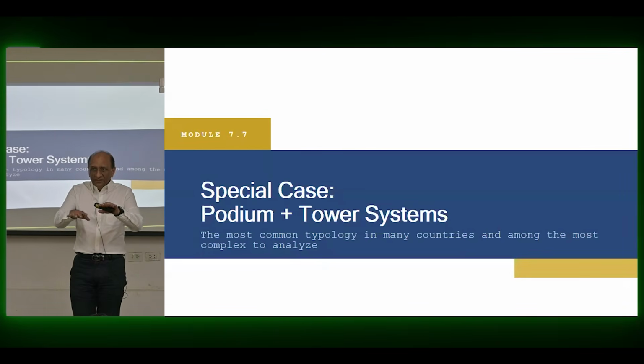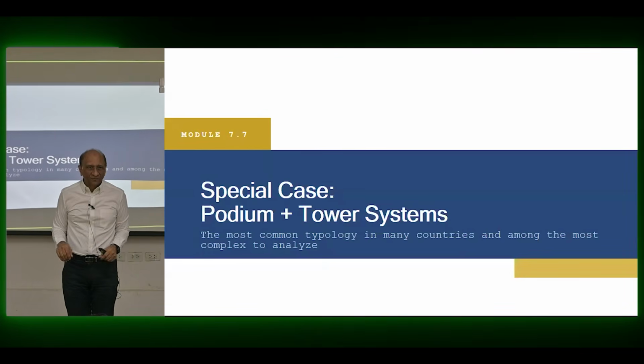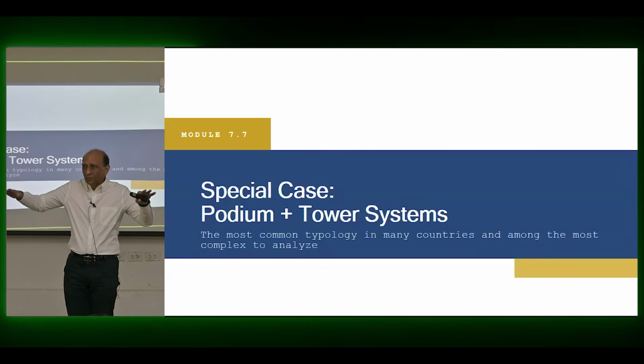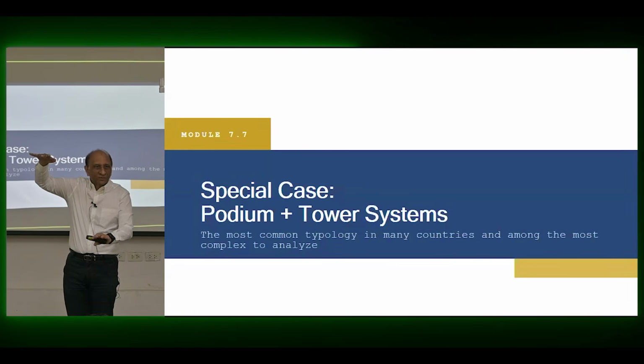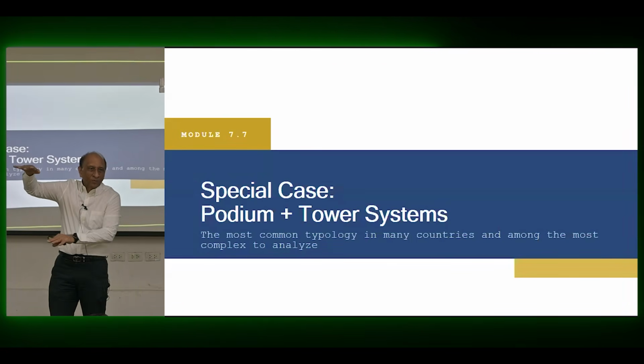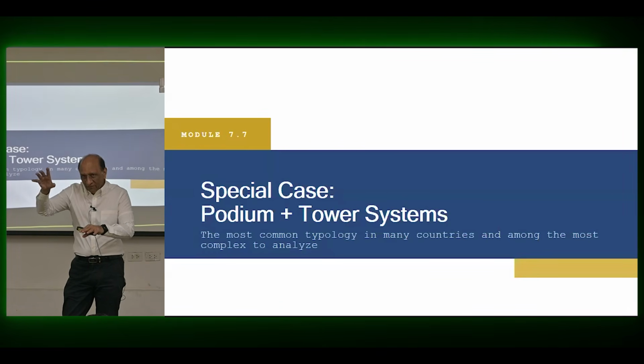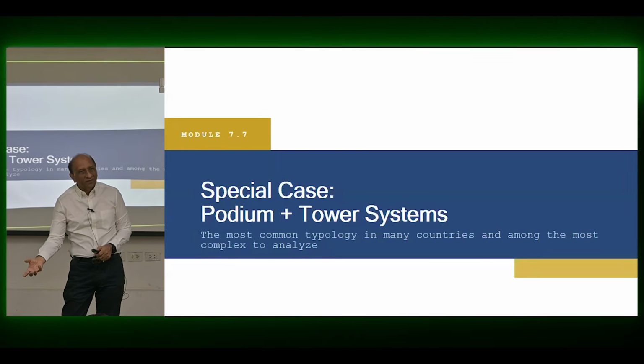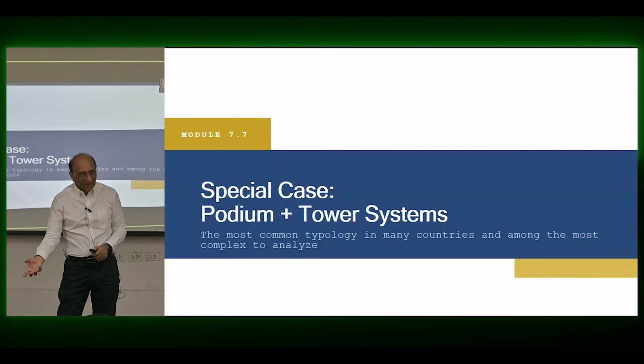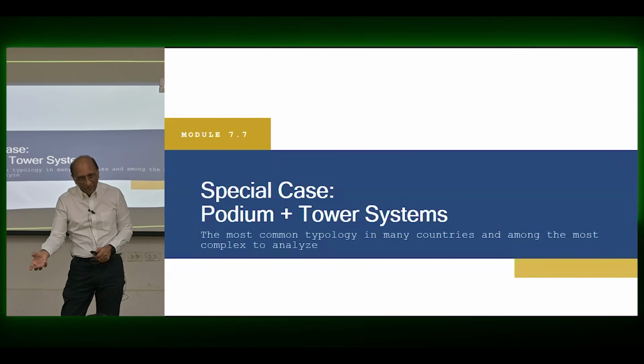Let's say the podium is the 6th floor. At the 6th floor, podium and tower are the same. And now the tower is going up, the podium is not going up, but the foundations are normally connected. So now the pressure levels on the tower will be increased substantially. So now they will start to settle more than this one.